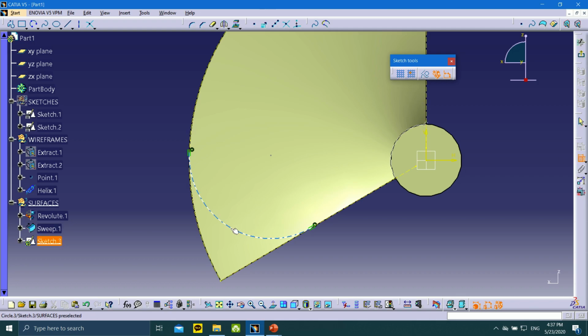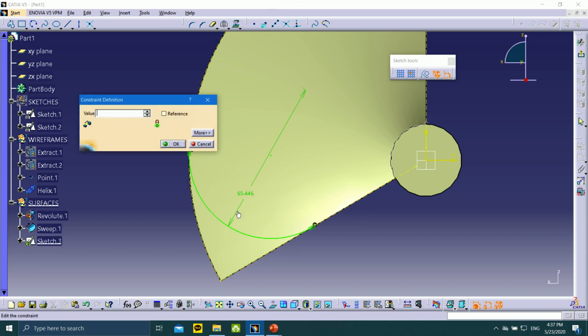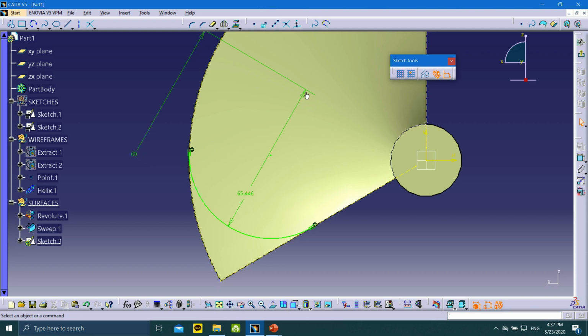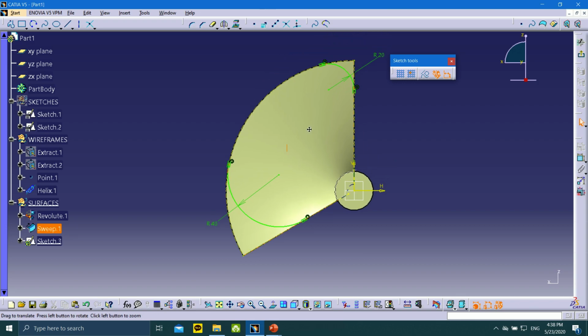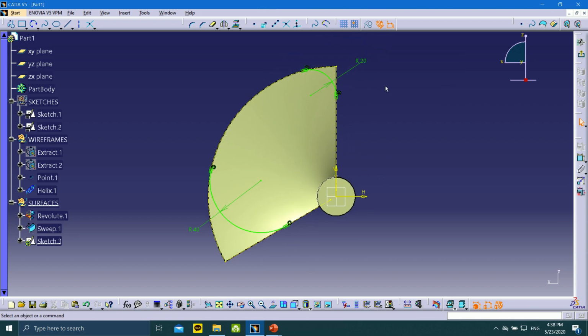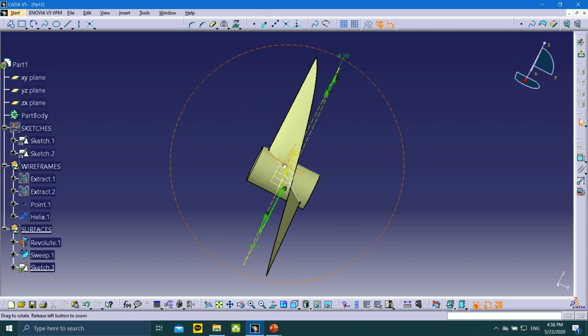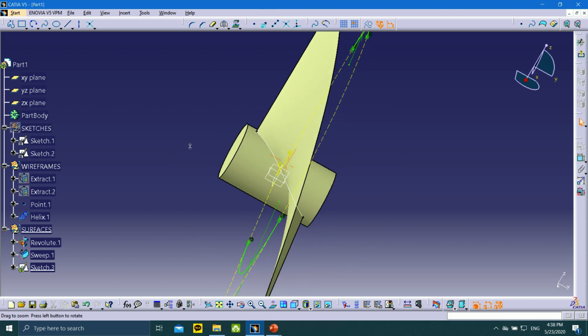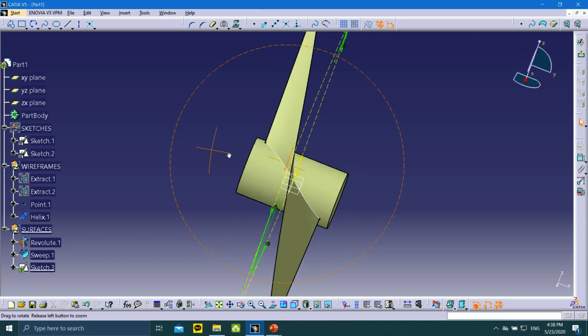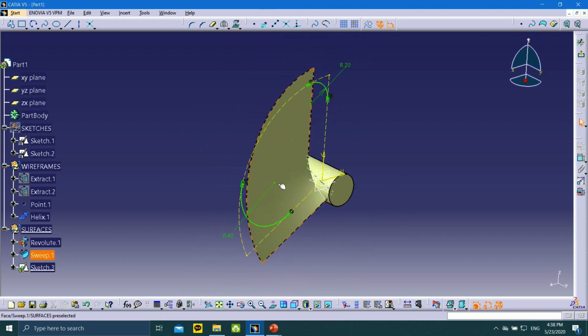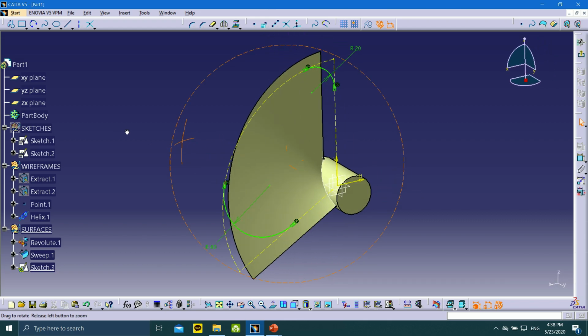You can create a dimension. Stupid dimension, I want to delete you. Really, this one is 40 radius. Okay, after drawing this, you can create a surface by extrude and cut the sweep surface. Okay, this one is basically your arc.